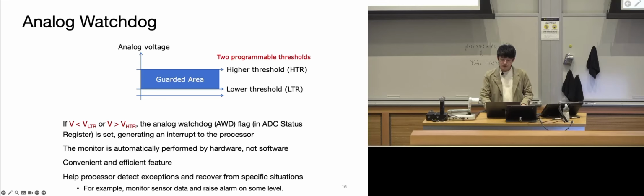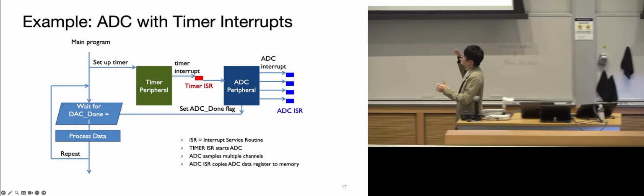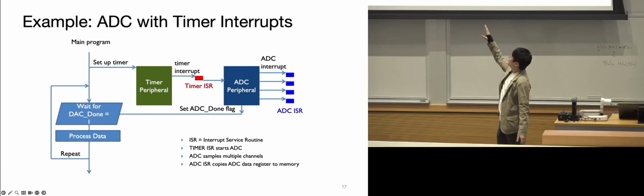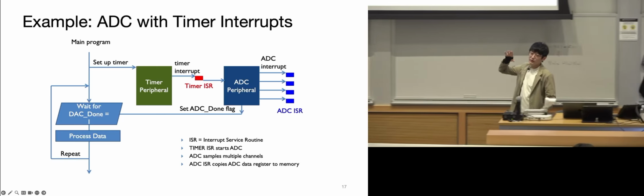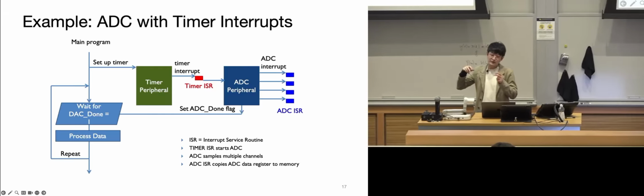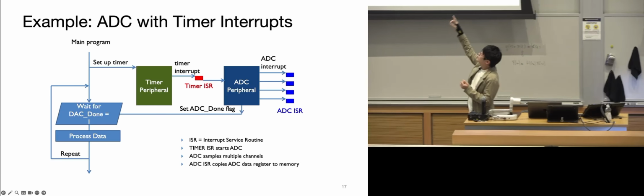Okay, cool. So if we zoom out a little bit, you have something happening on the peripherals, and an interrupt happens. The ADC peripheral will be called to do the sampling, and this is one way to do this. Essentially, the interrupt goes to the ADC.